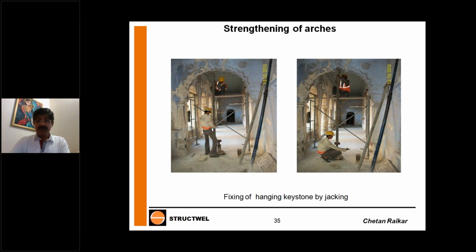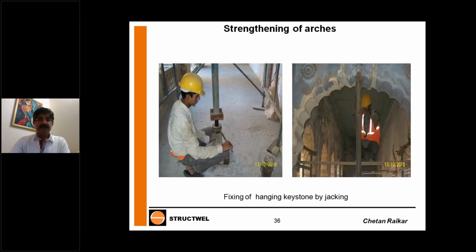This way we could protect the crown stones, push them back into position with practically zero cost. It's just the cost of 2 laborers. Actually the first 4 or 5 locations we had to physically stand there and show them. Then this team of 4 or 5 trained laborers were pushing the crown stones back all across. 500 crown stones, very limited cost. This is pure structural engineering.